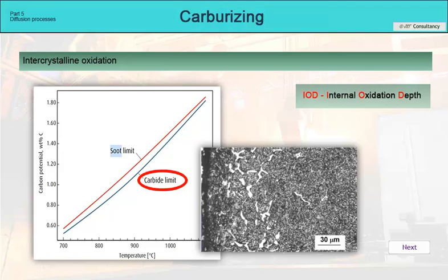It is necessary to take into account the control of the atmosphere according to this graph, because the saturating ability of the atmosphere must not be overdone, precisely with regard to the possibility of precipitation of secondary cementite, or even worse, with regard to the precipitation of carbon in the solid phase in the form of soot.